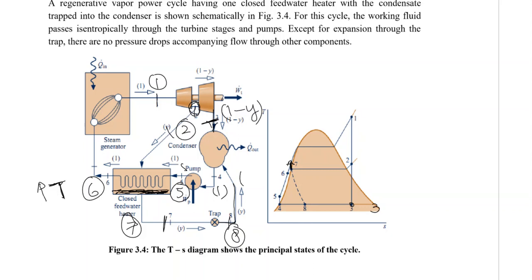So now if I'm saying we have got a feed water at 6, which is at higher pressure. Now if you want to put this saturated liquid in a feed water line, you have to increase the pressure. This is called a feed forwarding system, when we are using the pump to increase the pressure to put it in a forward line.